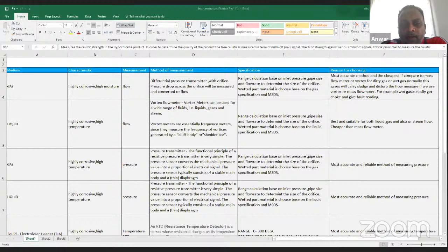So you need to understand the process that you have downstream. What is the level control requirement? What is the buffer volume you need to maintain in the tank, and also the point that you transfer, so that the effective flow rate could be determined later for this pump.